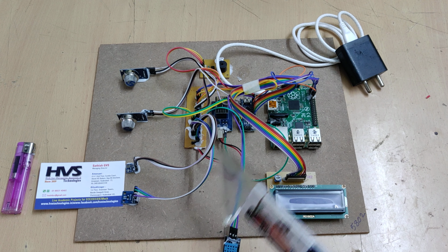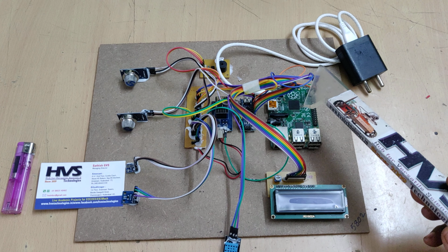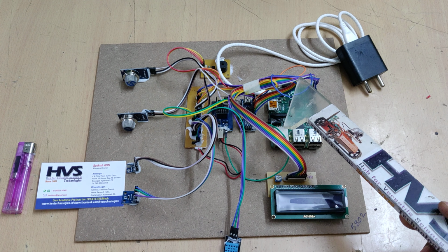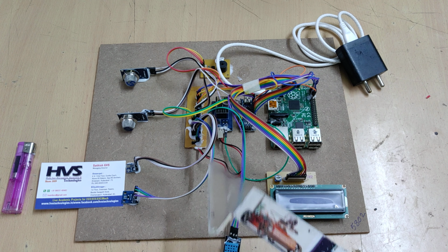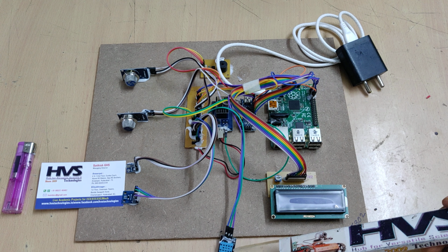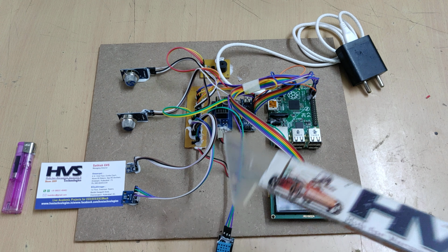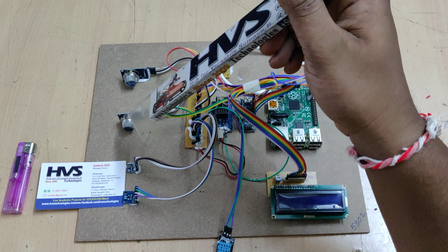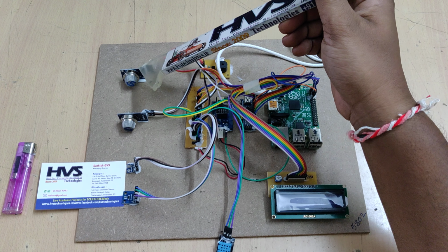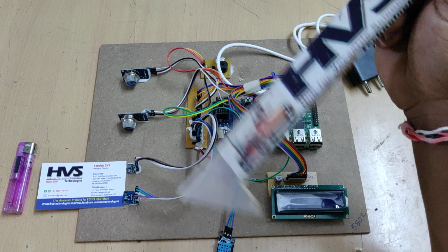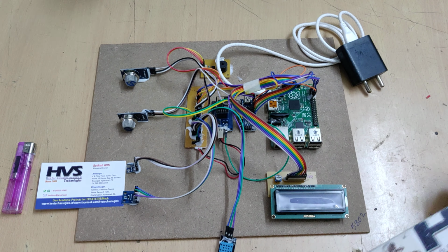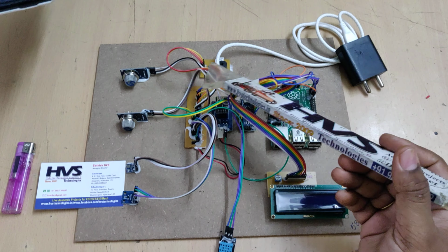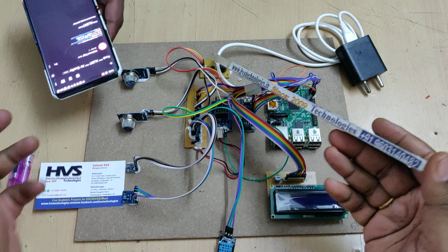We are also going to upload the data to the ThingSpeak cloud platform. That is the first IoT feature, and the second feature is, if any abnormality is detected from the sensors, like high temperature, high humidity, heavy air quality abnormality or gas leakage, then based on these conditions the system will send email alerts to the registered email ID, and it will also provide a buzzer indication from this piezo buzzer.